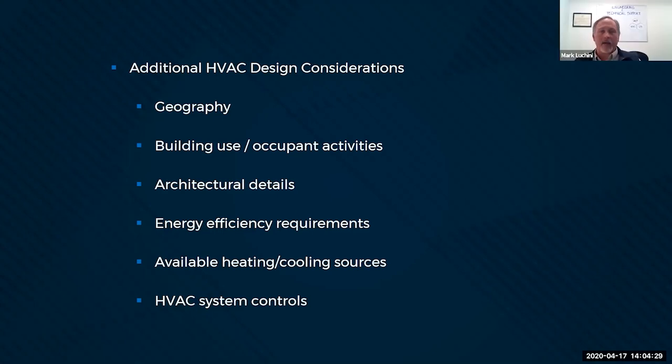Yep. Not too often you get 85 degree water, except, I don't know, maybe in Florida. I don't spend a lot of time there, so I wouldn't know. It's been up in the mid-80s. That'd be nice, like bath water. But even then, Joe, a cooling tower can reject that heat on an 85 degree day. So there's no reason that an 85 degree ocean couldn't take the same amount of heat output from a chiller. Right?